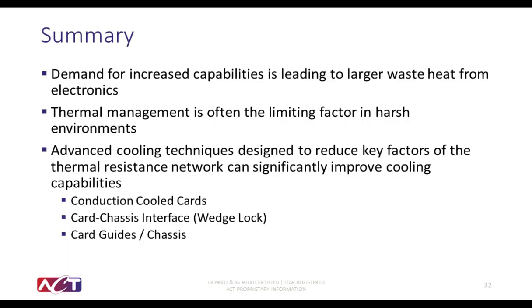Now, as demand for power increases and capabilities continue to rise, the need for proper thermal management does as well. Advanced cooling techniques such as heat pipes, high K plates, vapor chambers, or the ICE-Lok offer the ability to reduce key factors of thermal resistance networks in embedded computing systems. These advanced technologies can significantly improve the cooling capabilities in the card frame, the card chassis interface, and the chassis itself.